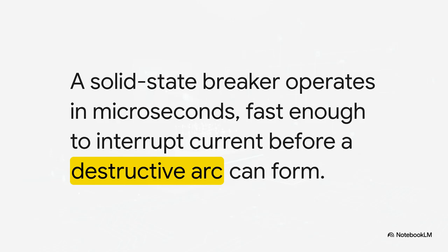When a mechanical breaker opens under load, its response time is measured in milliseconds, during which a destructive electrical arc forms. A solid-state breaker operates in microseconds, 1,000 times faster. This speed is sufficient to interrupt the current before an arc has time to ignite, preventing the associated damage.